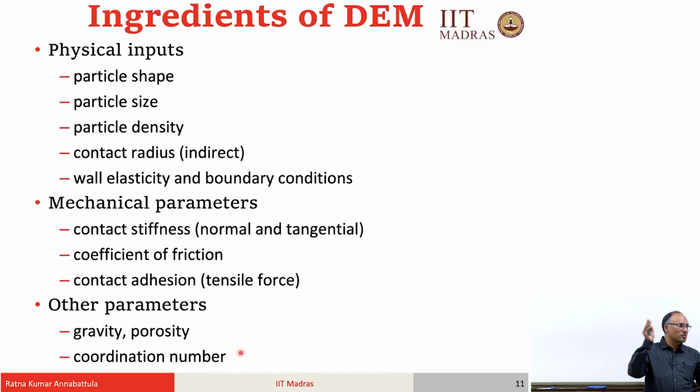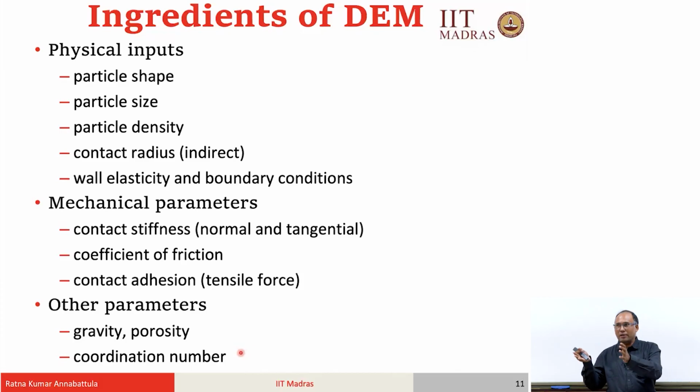You can only measure the force displacement response, and you do a DEM simulation and get the force displacement response. If your force displacement response obtained from the DEM simulation matches the experimental data, provided you have taken all the properties correct, then you have some hope that, because my macroscopic response is matching, whatever is happening internally makes sense.